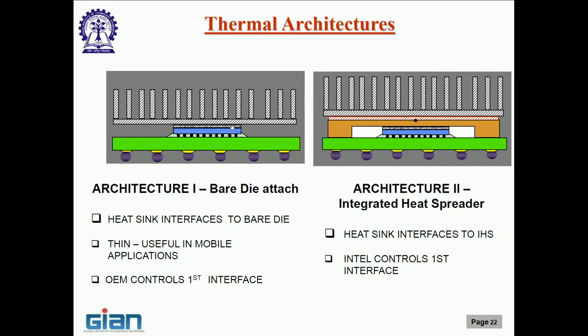Okay. You can cut it, take a small piece of the area equal to that of the die, put it on top and put the heat sink. When you power on the die, the material is such that it melts at a temperature, let us say 45 degrees for example. So, of course, your die is going to go at a temperature higher than 45. So, this material is going to melt, but it is very viscous. Okay. Since it is so viscous, but it melts, it becomes a little fluidic state.